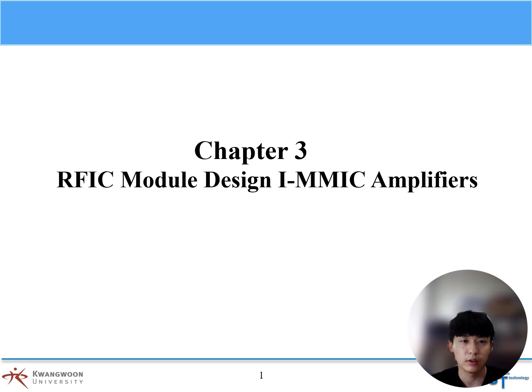In this chapter, the basic theory of the MMIC amplifier is presented, including descriptions of DC bias injection, classical stability and gain analysis. Different types of noise, such as thermal noise, shot noise, flicker noise, and propagation noise, are briefly reviewed. And lastly, the practical designs of the MMIC IF amplifier, the cascode low noise amplifier, and the three-stage power amplifier are illustrated.